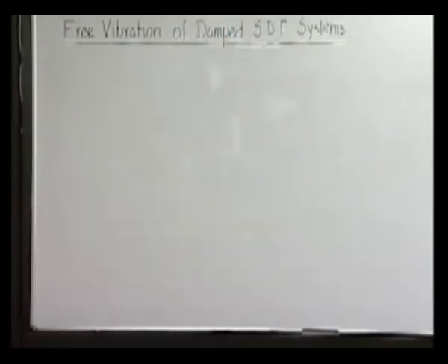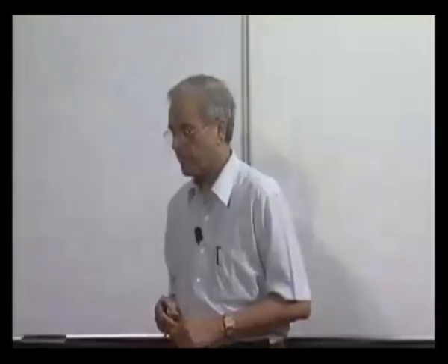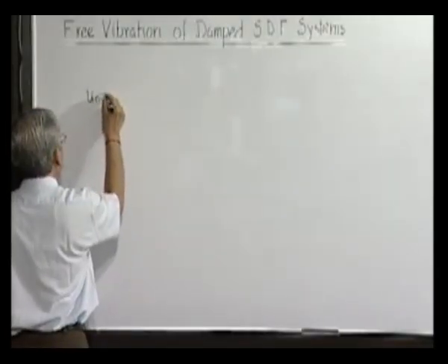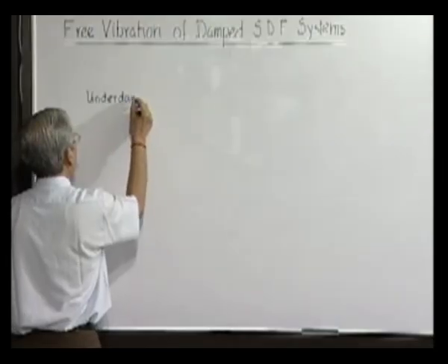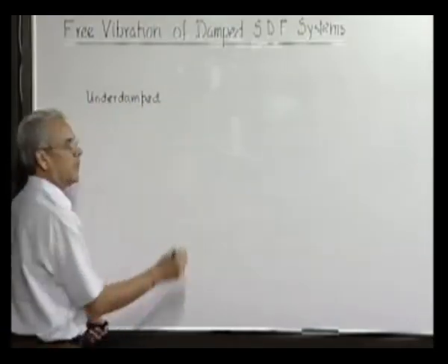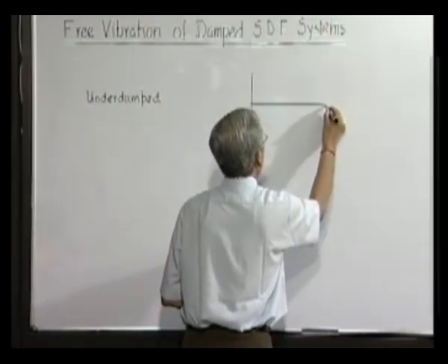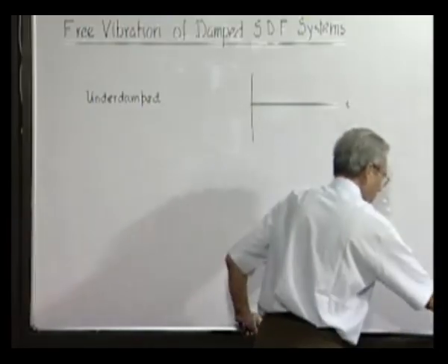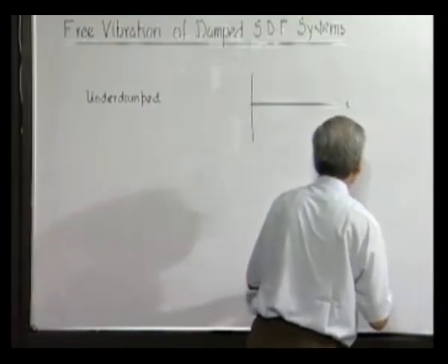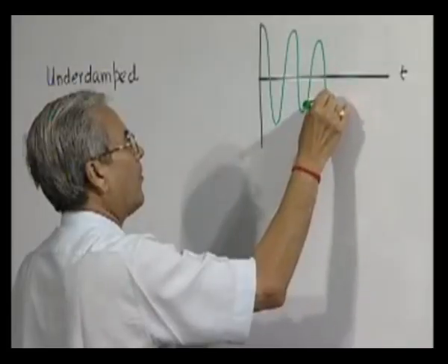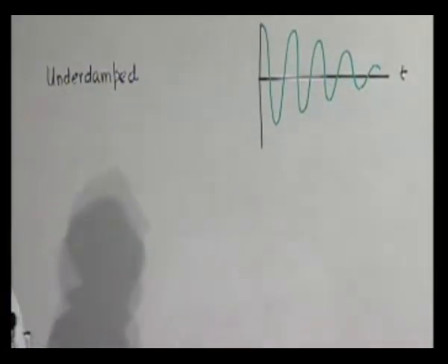So, now to sum up the matter concerning the viscously damped single degree freedom system free vibration problem, we have seen that cases can be underdamped, and in the underdamped situation the oscillation of the system decays like this.